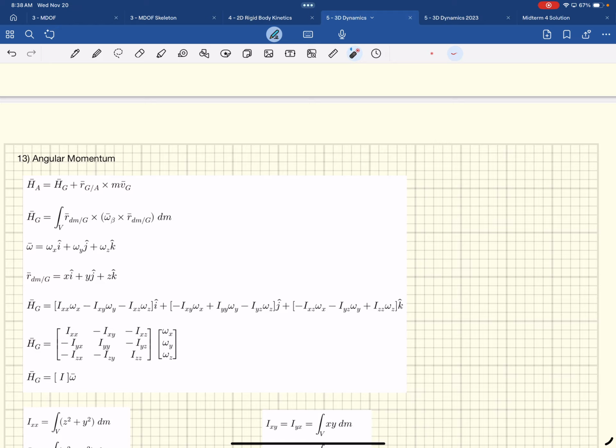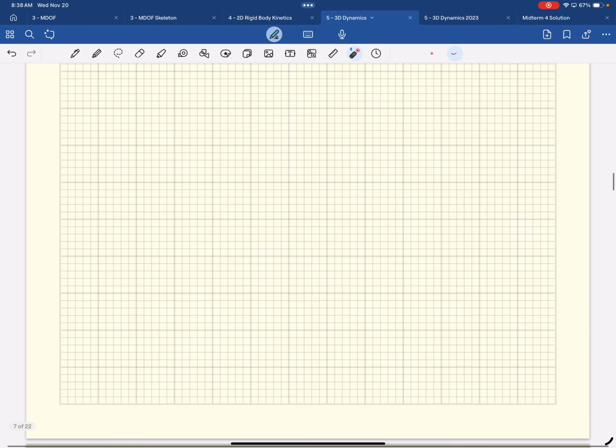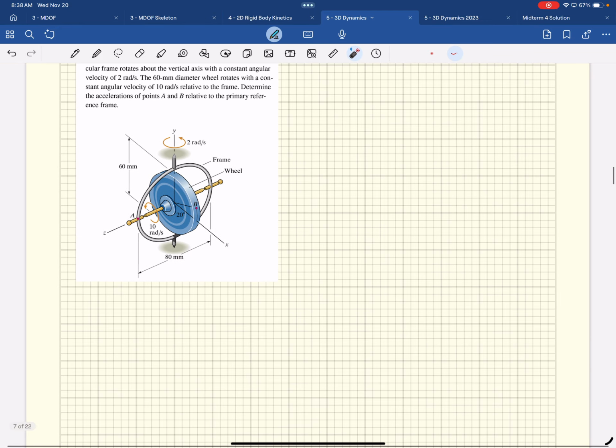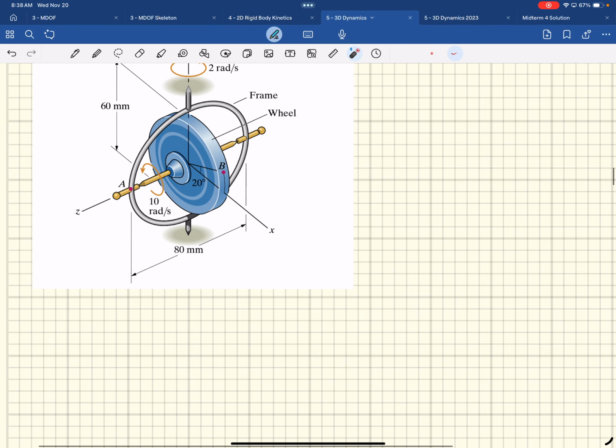It's taking a step from one point to another point. All the problems in the book fall into that same category. This is one of the most complicated ones they had. If I was after the acceleration or velocity at point B, I know that the velocity in the very center of this thing is going to be 0, so I just take a step from here out to here.